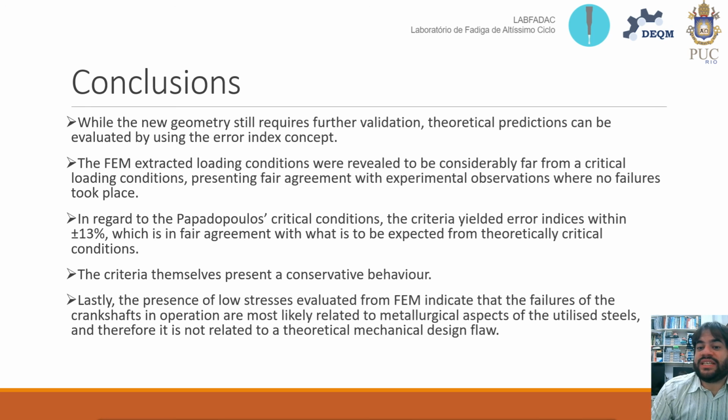Despite not having all the desired experimental results, a theoretical analysis is still very effective. The finite element method loading conditions yielded error indices that are very negative, meaning that the crankshafts do not fail as a consequence of inadequate loading conditions in operation. The other set of loading conditions, considering real fatigue resistance limits, yielded average error indices close to nil, but still indicated that the models tend to be slightly conservative.